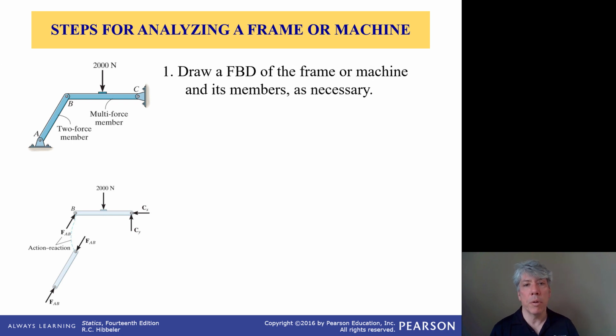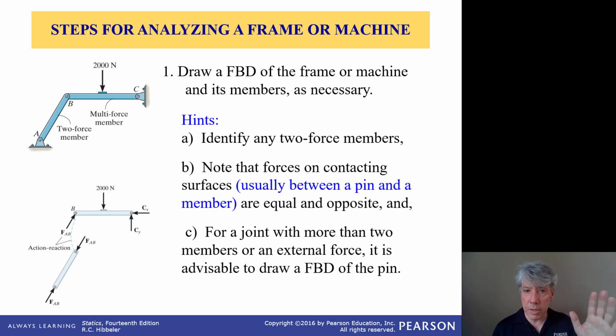So how do you go through and analyze this sort of device? First things first, draw a free body diagram of the frame, its members, the machine, whatever you need. Draw a free body diagram, and sometimes you'll have to start the process with one free body diagram and change to another free body diagram in order to determine internal forces. But draw them as needed.